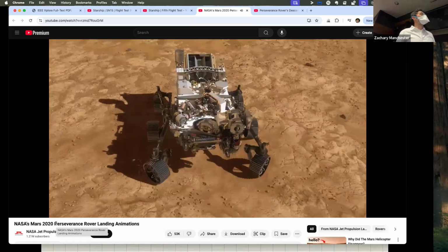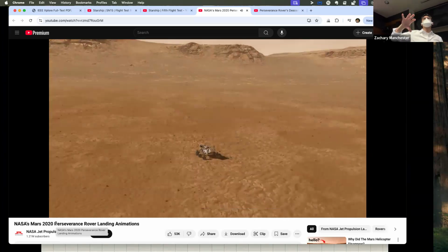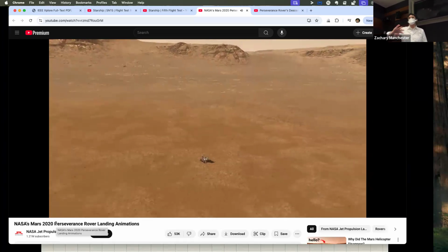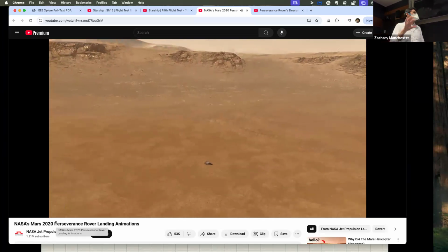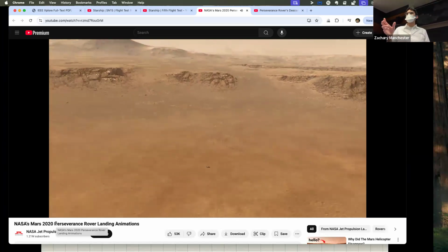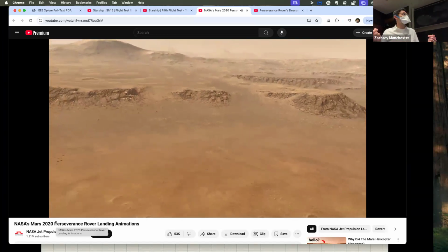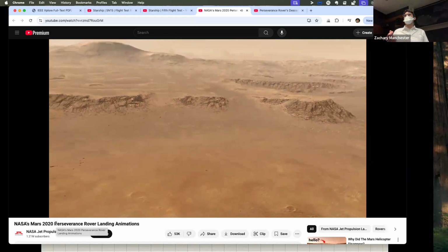Kind of cool. The part we worked on that we wrote a bunch of papers on is the entry guidance phase. So that's the fireball part. It turns out you can steer in the fireball phase to try to reduce your error, but you don't have any state estimation. So the tricky part there is you have about 1 kilometer uncertainty when you hit the atmosphere, huge uncertainty in the atmosphere, and you're just dead reckoning with your IMU.